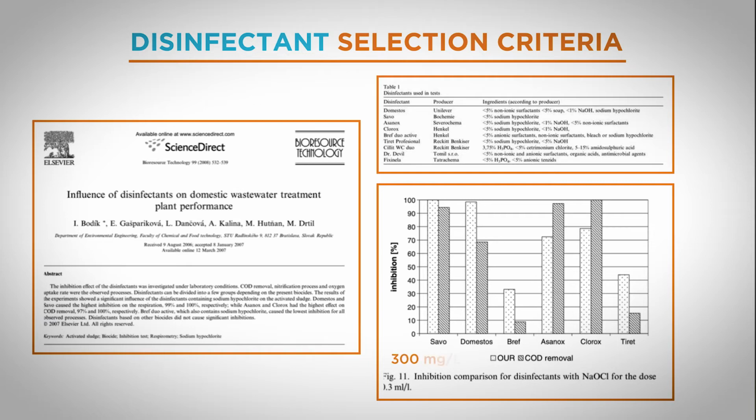They found that 300 ppm of chlorine, and remember, in disinfection, we're talking usually about 1,000 to 2,500 ppm of chlorine, but 300 ppm of chlorine in that wastewater actually inhibited the ability of the bacteria to process the COD, or the chemical oxygen demand, by levels of up to 70 or 80%. To me, this is a very important finding.